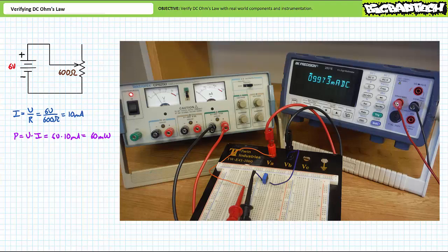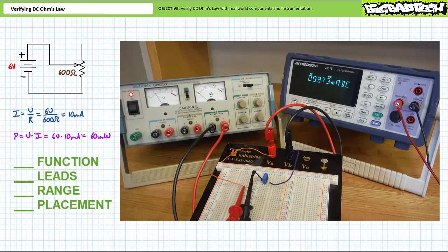Beyond the theoretical understanding of Ohm's law and a general familiarity with potentiometers, protoboards, and DC power supplies, you'll note observation of this circuit required the use of 3 different aspects of the DMM, specifically the ohmmeter, the voltmeter, and the ammeter. Additionally, it necessitated we seamlessly and flawlessly switch from one mode to the other without breaking anything or getting hurt. You'll note we did so by routinely employing the checklist each and every time. I am not urging you to use this checklist every time. I am demanding you use this checklist every time. This checklist will save your measurement equipment and circuit a lot of costly downtime and may potentially save your life.